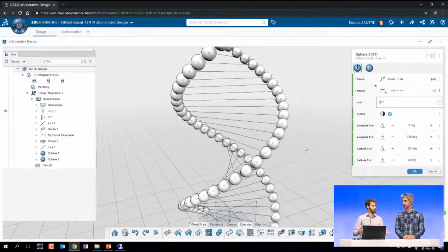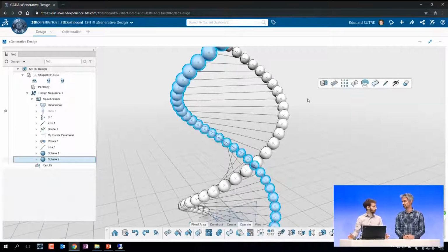And something interesting also. You can validate clicking the OK button, but in fact there are also a lot of simple tricks, accelerators, in order to rapidly model some complex stuff. Like for example, good to know, you can double click in the background to validate. It's something really powerful.